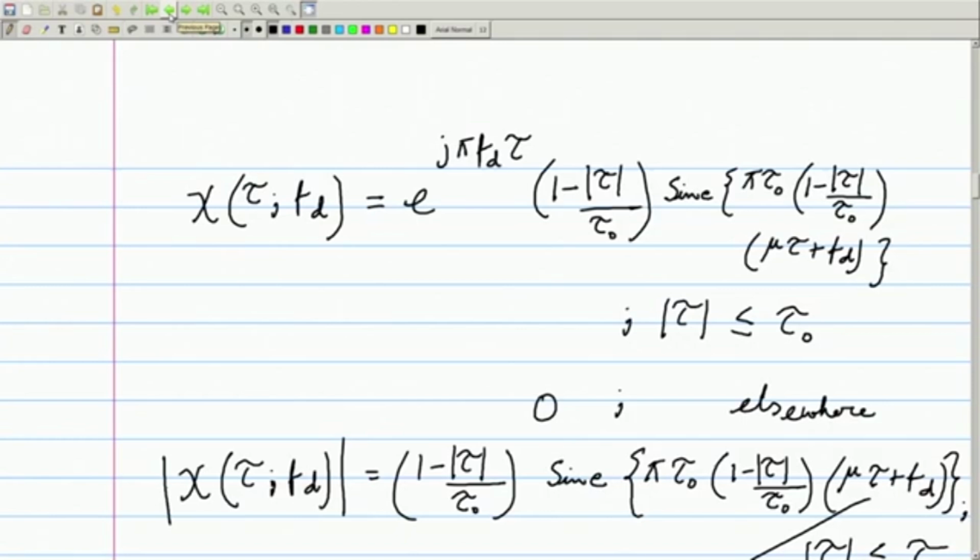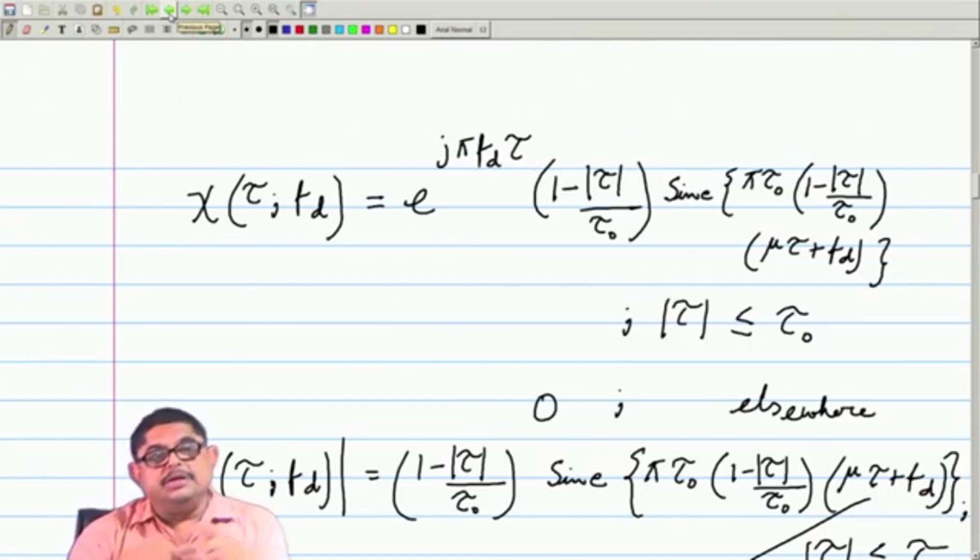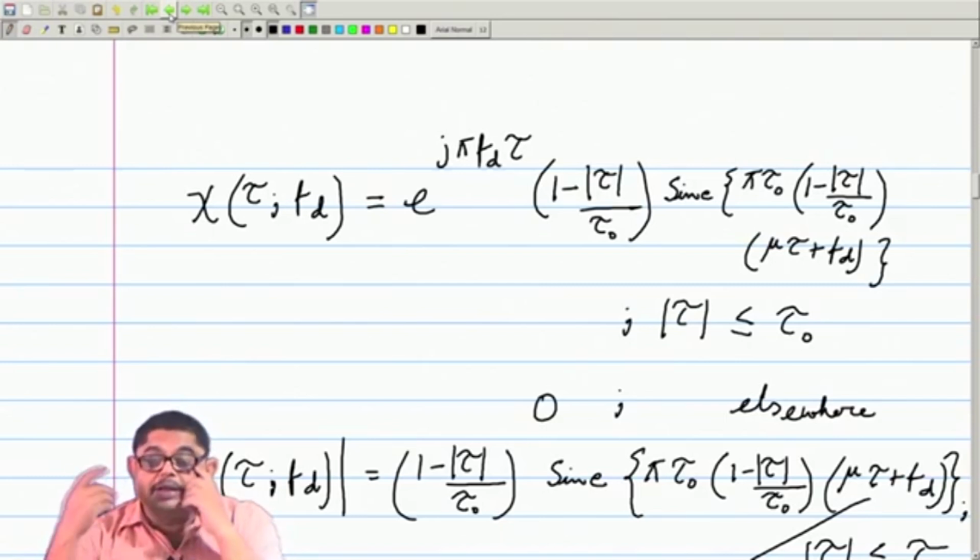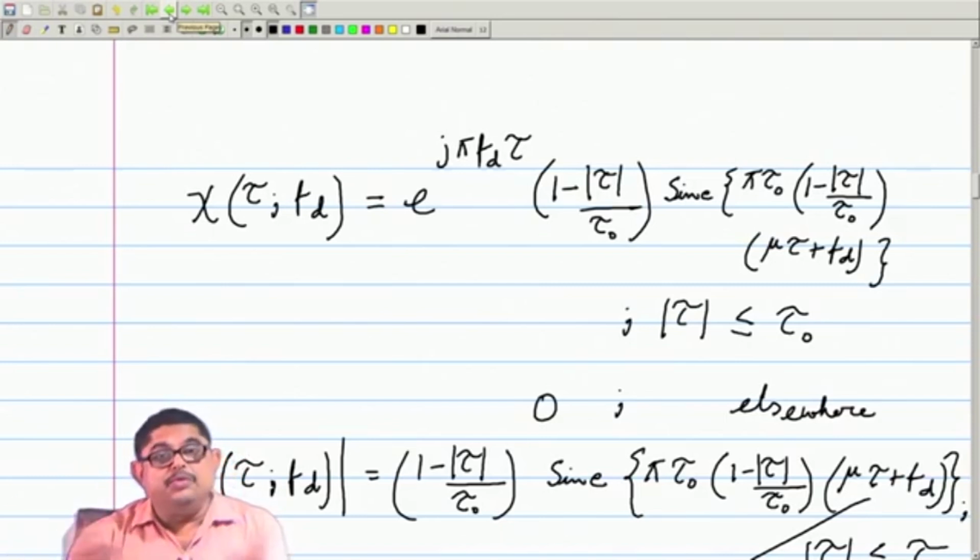So, this is the same expression that we could derive. Here we have derived from first principles, there we could have done it by using the property of LFM, that if you give a frequency modulation, that means a phase of e to the power j pi mu t square, then by using that property in one line you can derive. So, by that actually people derive the ambiguity functions of various new type of signals and find out their effects as far as the thing goes.